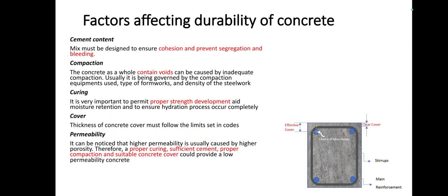So the next one is curing. Curing also plays a major role. Why should we do curing? To make the concrete achieve its target strength. If you are not doing the curing, what will happen? The water which is meant for the hydration process will evaporate out, and thereby the desired strength cannot be achieved. There are many methods of curing, as I told, like water curing, membrane curing.